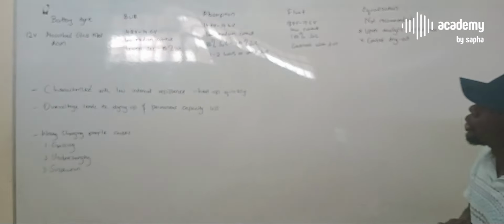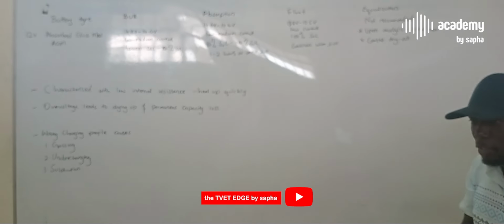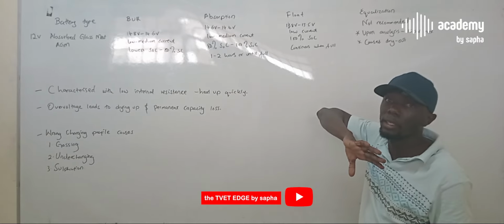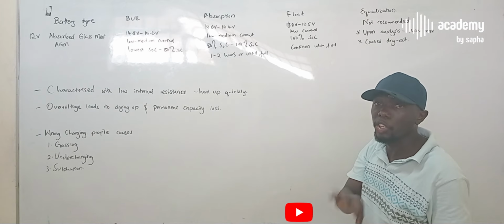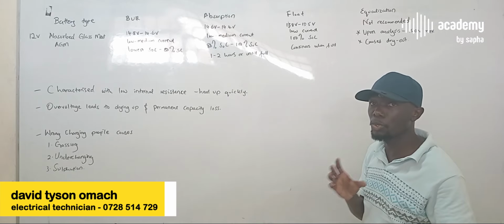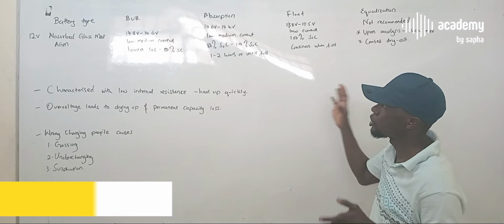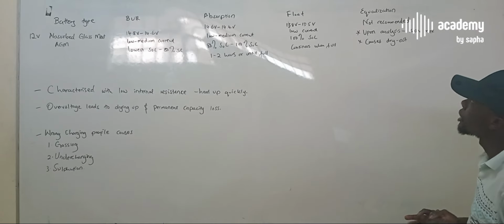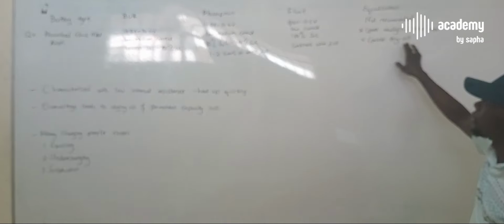If you're actively utilizing an AGM battery and it's charging at 13.5, you are undercharging it in that case. Now, I think from this point you start understanding why even the voltages themselves have to be controlled for this system to charge effectively. So for an AGM battery, there's no equalization, because equalization causes dry out.